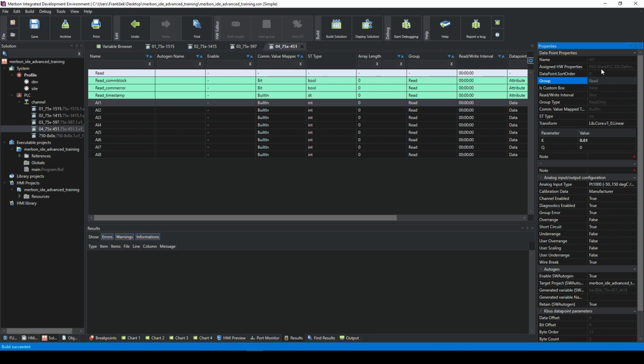So for example, if you want to measure resistance, you'll have to buy a resistance card. If you want to measure current, you will have to buy a current card. So you have to buy it in advance. There is no option to change it if you already bought the card. The card is made to measure just one type of measurement. So this is one of the differences, I think the biggest one, from our previous IOs and these ones.